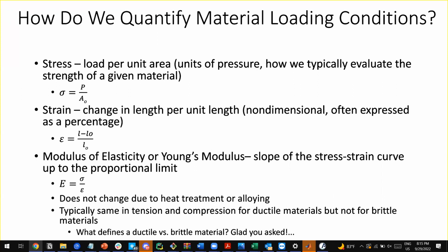Parts fundamentally fail because of the loads on an atomic level. And those loads are dependent on the pressures that the part sees, or the stress, as opposed to just the pure forces. If I had two rods of different diameter and I applied the same force to them, you wouldn't expect them to fail in the same way, right? But if you normalize that description to pressure, then that allows you to predict the failure of both parts in a consistent manner. So in general, stress is really just a pressure. It's the load on your part over the area at that interface.